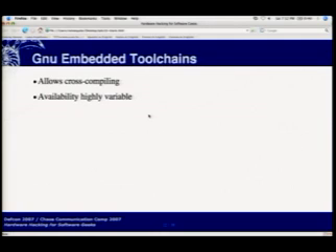That's very important because none of these microcontrollers will use the same instruction set as my x86 laptop here, because x86 is almost never used in embedded applications just because it's overkill. An overly complicated instruction set, a lot of pins, just a lot of legacy stuff in it. I actually use a cross-compilation toolchain for working with the AVR microcontrollers that uses AVR glibc. It's all open source stuff, so it's free, easy to come by.